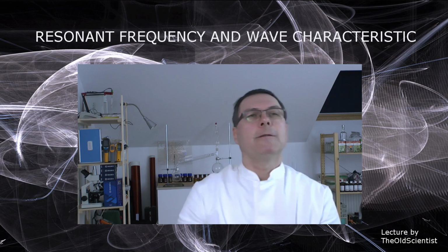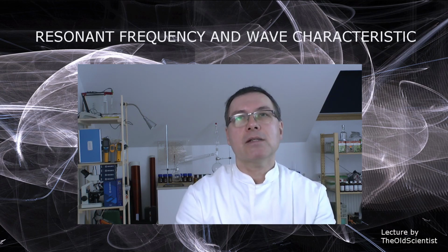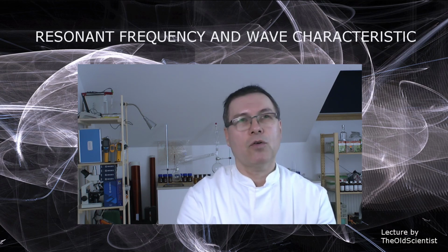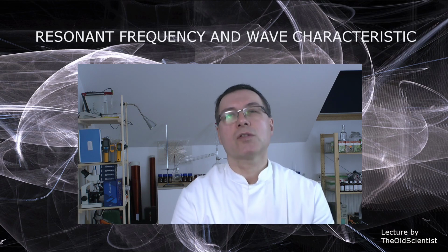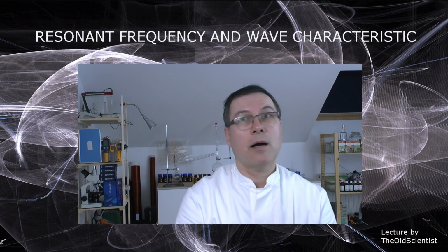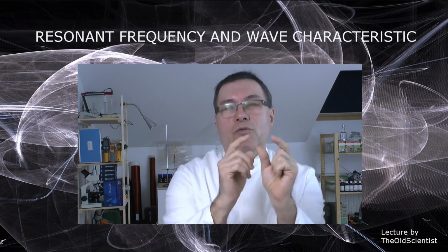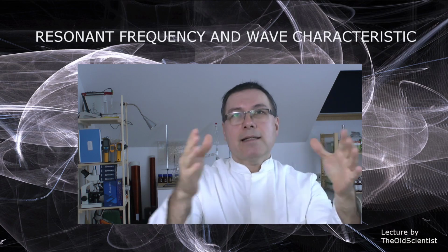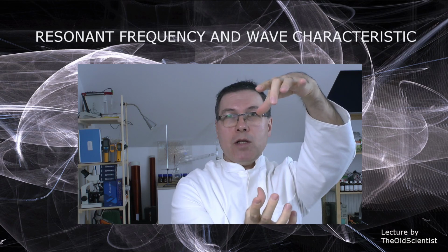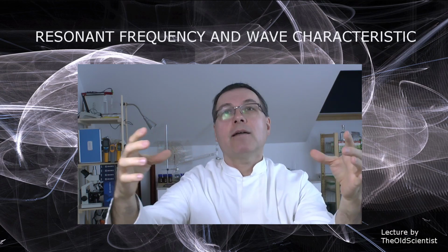So okay, high frequency in a coil depends on the size and dimension and the amount of wire and windings you have in a coil. If you want to have a high frequency coil in a megahertz range, you can use only a couple of windings. It has to be small. Also, the ratio between the windings itself to the distance, the width of the coil, the length of the coil, they need a specific ratio for the frequency.